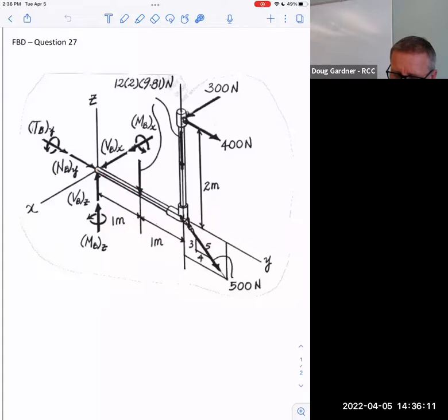So is there a normal anywhere else? Kind of like in line with the pipe, but I'm not seeing one when it goes into the Z axis. Like I would think there'd be a normal. Well, it's got to be parallel. It's parallel to the linear piece that you're chopping. If you decide to take this pen and chop it right here, then automatically a force in that direction is called normal. A force in this direction is called shear. Because of the nature of what breaks it, and because, strength-wise, some materials break more easily in shear than they do in tension, a normal force. And so that's why the distinction.